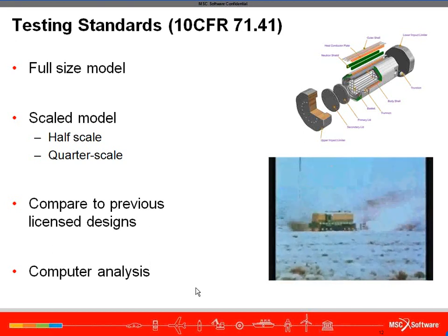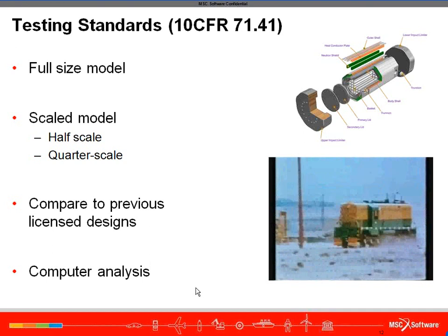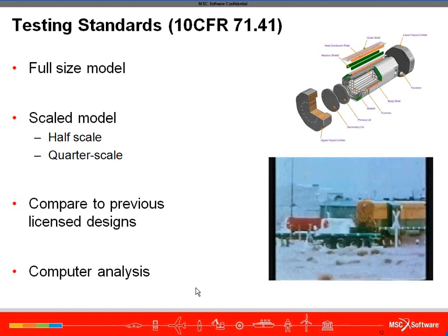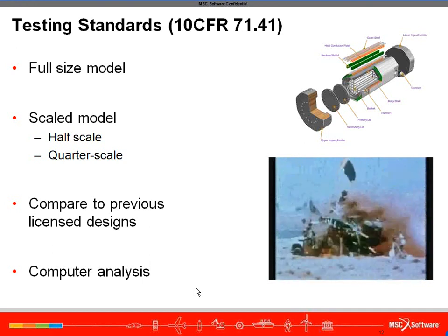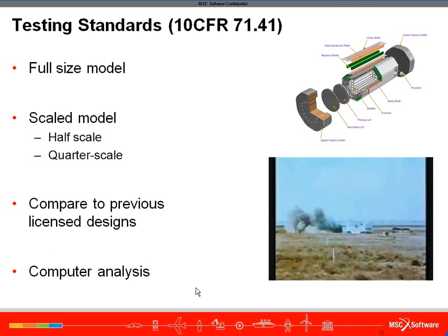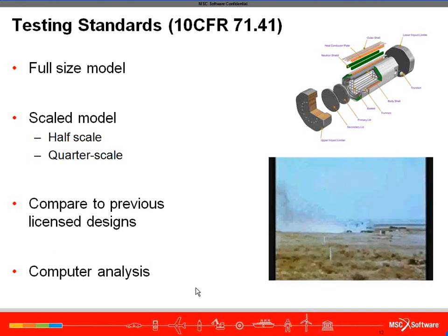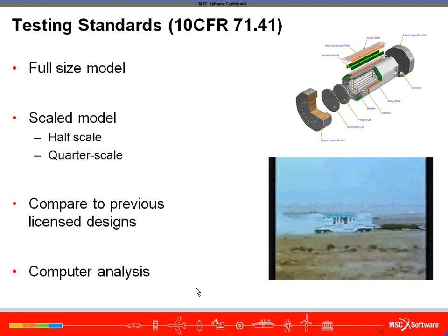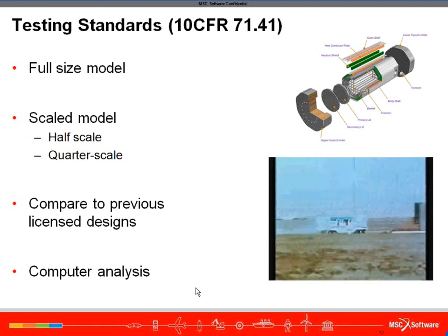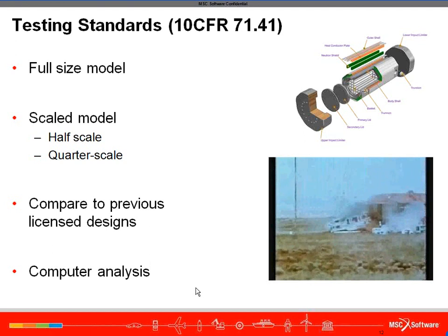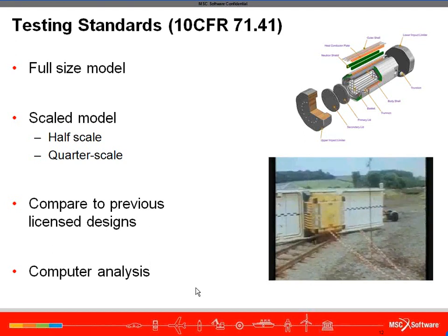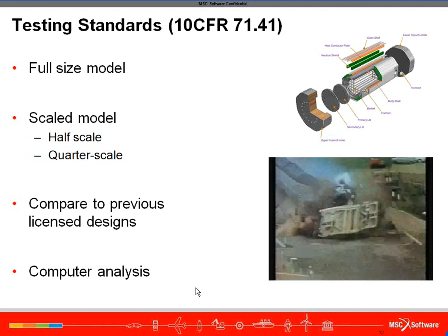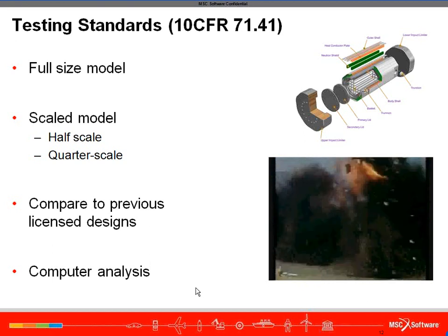In many cases, this can be estimated to be the orientation that would be the most severe to the cask limiter, as at the moment of impact, this orientation would result in essentially a point load, so extremely high loads and stresses. The corner drop in that video was followed by a typical pin drop, and it'll come back around in just a second. And that shows the pin that we talked about penetrating the limiter and ultimately contacting a cask.